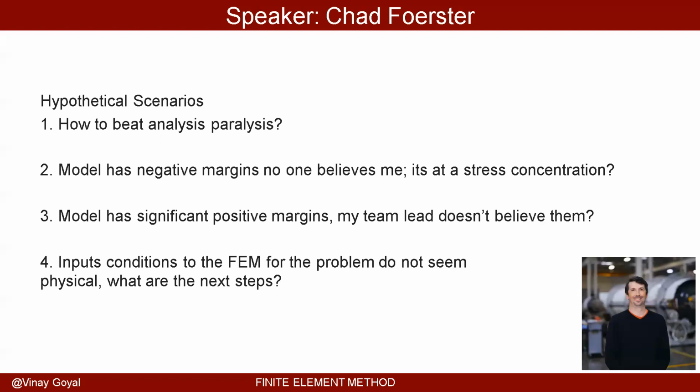Then look at whether you can use certain types of elements to make your solution better using fewer elements. There are certain elements within Abaqus, for instance, that are pretty useful because they have extra shape functions in them that are different than a normal hexahedral element. They give pretty good results, and the computational increase is not that much. Those are the two things that I look at.